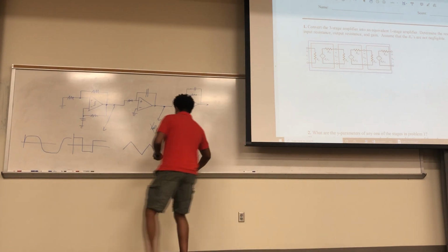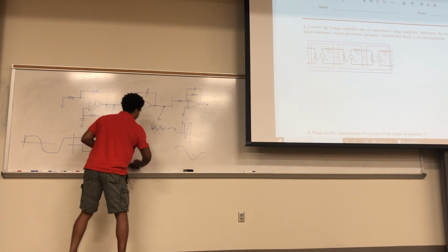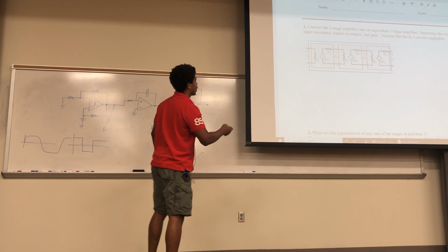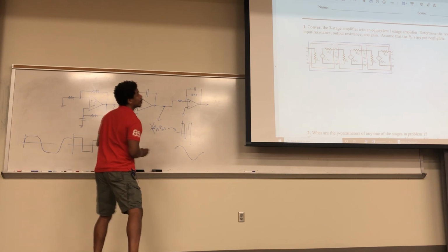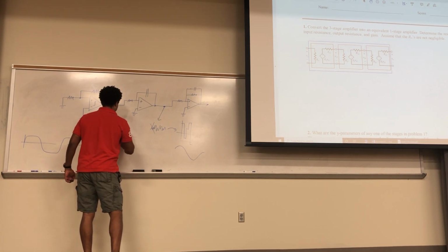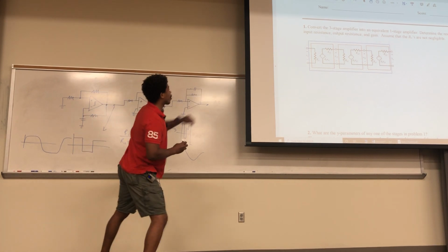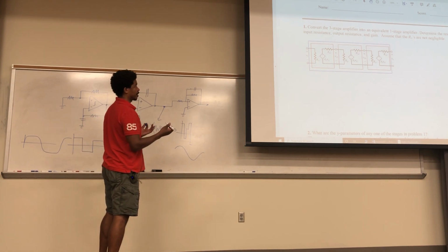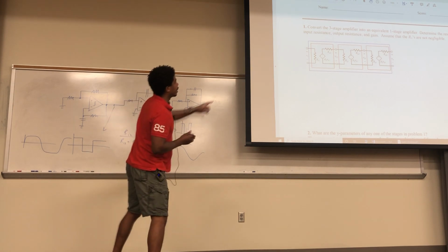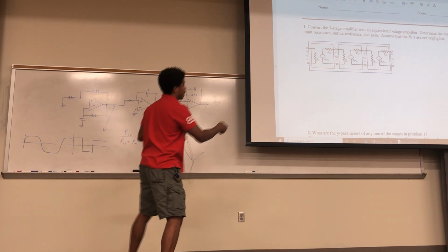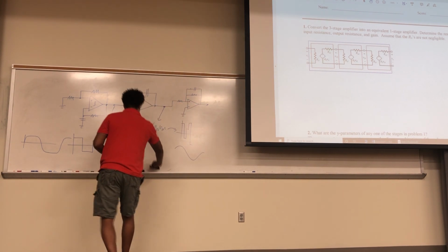And let me just show you why that's the case. So, for example, this first one right here, with that one right there, we had Ri2 over Ri2 plus Ro1, and we did our voltage division with that. So you're starting at A1 Vi1. I'm looking at it right here. You're starting right there.